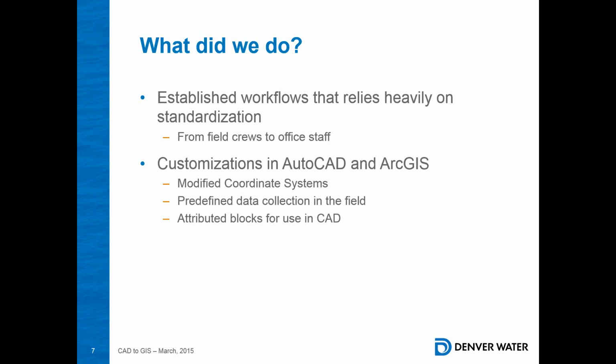So instant CAD file, and I can start using that CAD file and overlaying Civil 3D or anything else that I want on it. But now I can turn right around using the export feature if I wanted to, and even export that as a shapefile with all the attributes and everything else. Correct. So it's a single line of data.